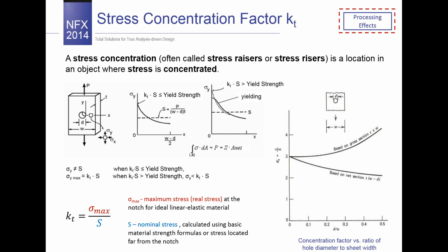So what kind of features are responsible for that? Features like holes, notches, shoulders, grooves that often cause this phenomenon are called stress concentrators. And there is a dimensional factor, which is known as concentration factor K. This factor is used to quantify how concentrated the stress is.